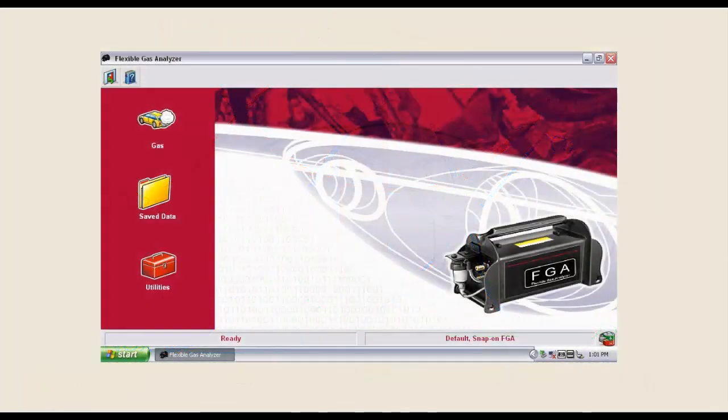We'll use a 5-gas analyzer to measure the emissions. It should be noted that NOx emissions should be measured with the engine under load. Since this testing is done on the shop floor, I would not compare this gas to a regulatory specification.